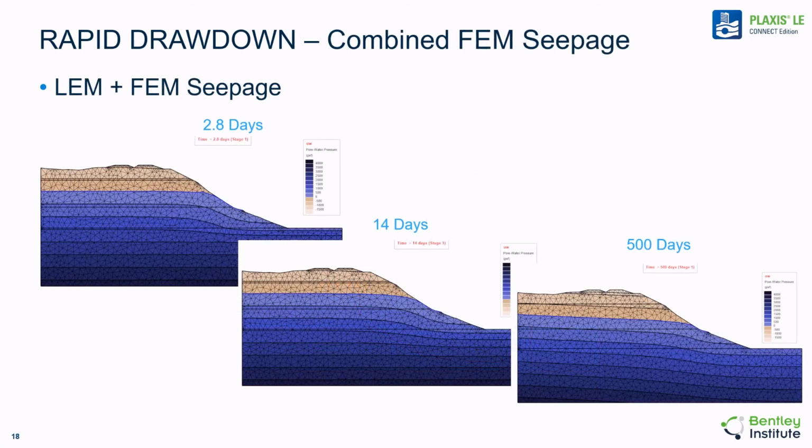If the hydraulic conductivity of the soil is known, then the time lapse to draw down pore water pressures in the slope can be computed using a seepage model. These 3 figures show the change in the water table over time. In this scenario, the change in water table is minor given the hydraulic conductivity present at the site. On other sites, the rapid drawdown effect may be larger.